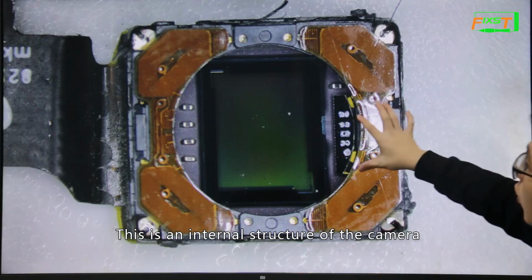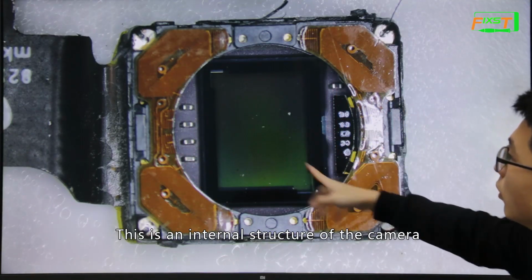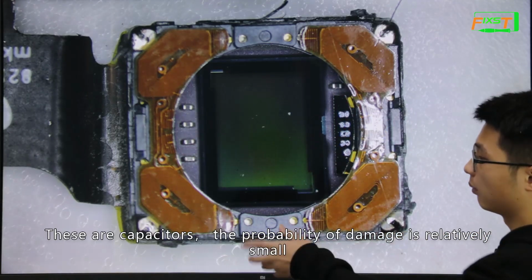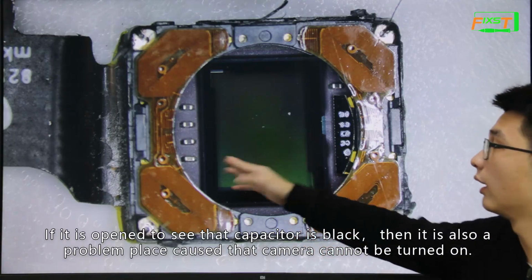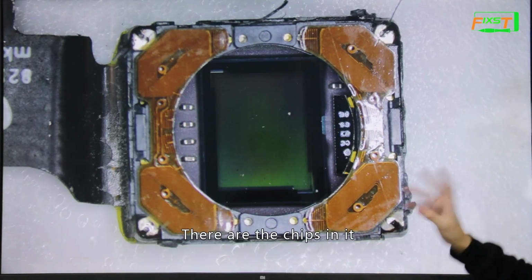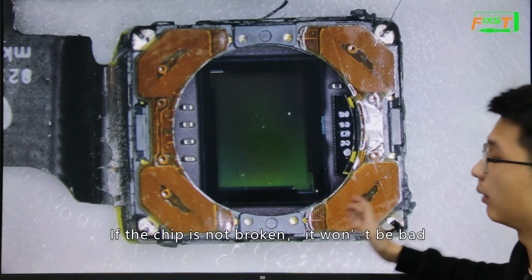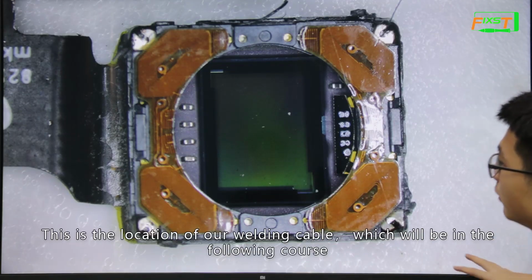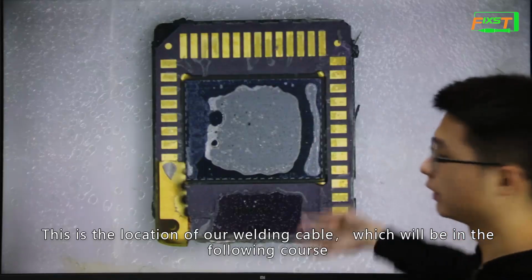This is the internal structure of the camera. These are capacitors. The probability of damage is relatively small. If you open it and see that the capacitors are black, then that is also a problem place that causes the camera to not turn on. There are the chips in it. If the chip is broken, it won't be fixable. This is the location of our welding cable, which will be in the following course.